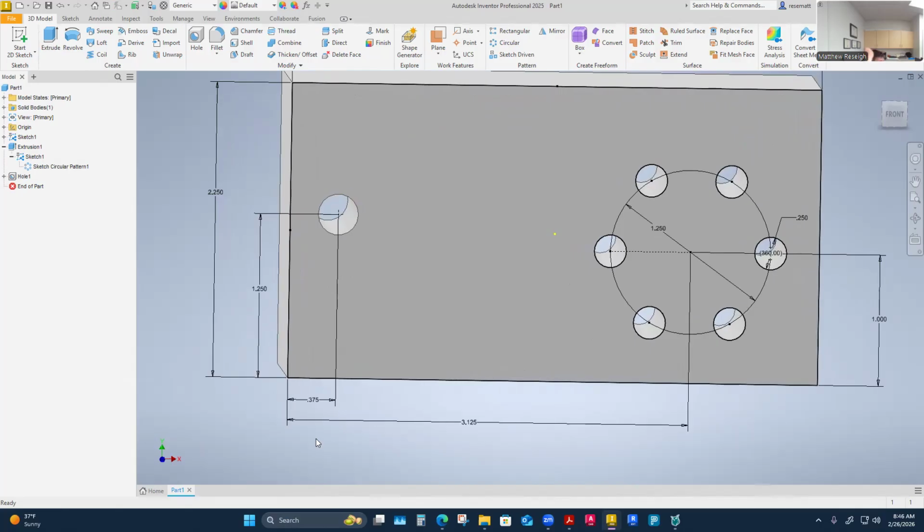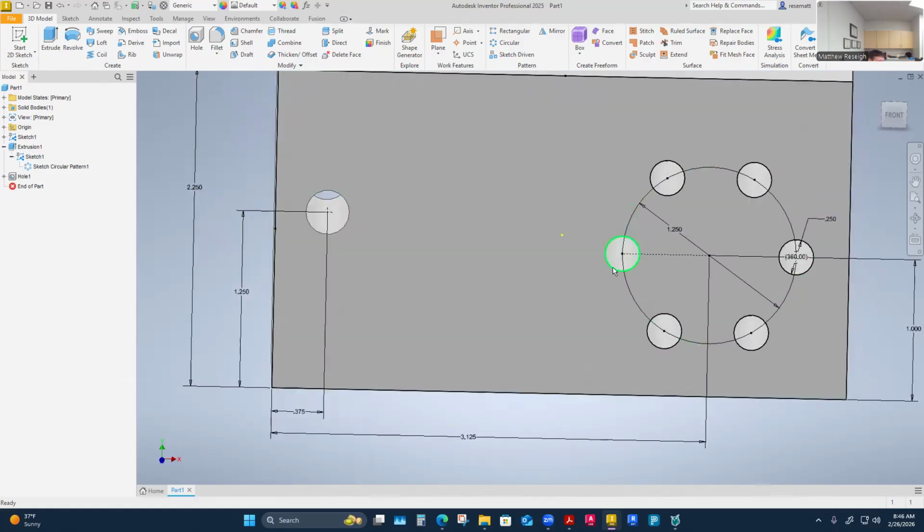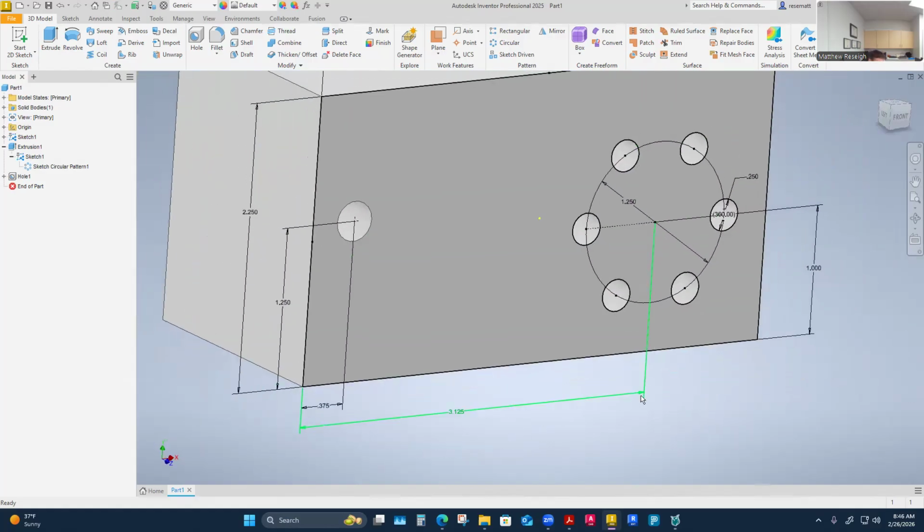At this point, it wouldn't matter either way, but I've chosen to draw these two hole sets just slightly different. One's in the sketch and in the extrusion. Which also eliminates, or maybe the way I might want to manipulate those holes later is a little less manipulatable, I guess, because that's what I found with my hole when I put it in. I was going to feature pattern that and I'm like, oh, I can't do that. It doesn't really consider that a separate feature, but this does now.